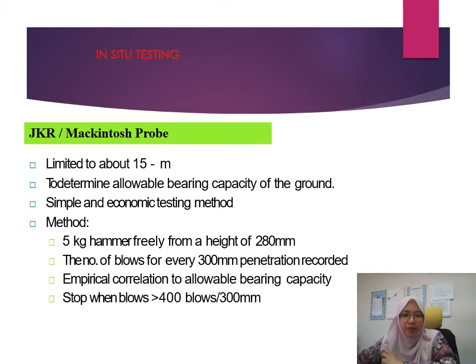Then an empirical correlation to the allowable bearing capacity can be done. So we can check the allowable bearing capacity with the number of blows that have been recorded.